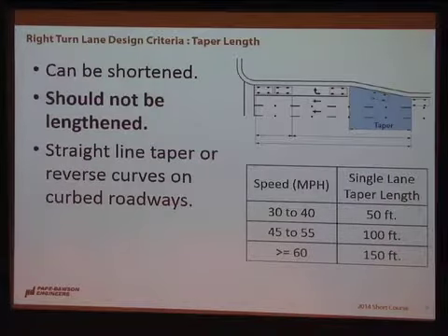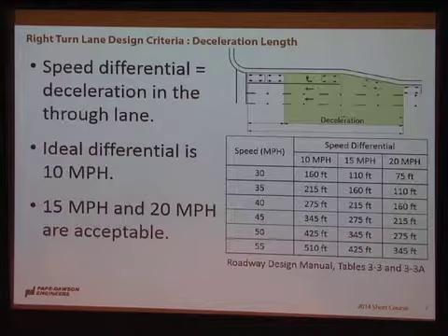Of course, use a straight line taper on most of your roadways. If you're using a curbed roadway, then you might want to consider a set of reverse curves that wind up with taper lengths similar to these that are presented. And those are all straight out of the RDM, or Roadway Design Manual.